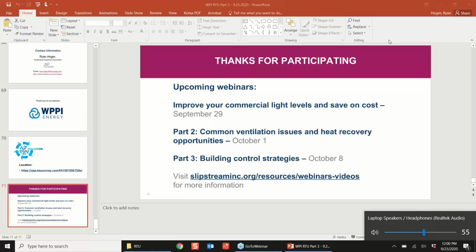An even newer way to do that would be a different type of fan. So you're going to start seeing fans like this. I don't know how well you guys can see that right now. This is a vane axial fan. Inside there's a variable speed ECM motor, although in this particular case, I'm not varying it. The controller in the unit is just running it as a 2-speed fan for the reasons that I said before. The economizer controller can only handle 2 speeds right now. So it's running in a 2-speed fashion, and I'm getting that accomplished without the VFD. So there's no VFD on this one, but it's doing the same kind of thing.